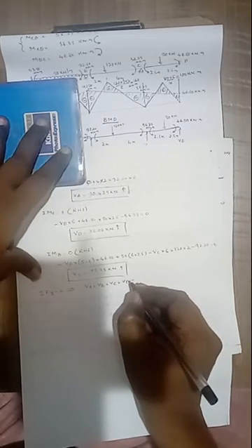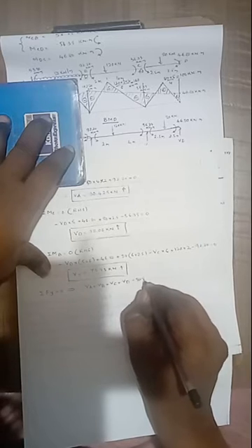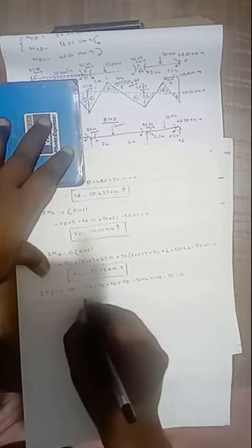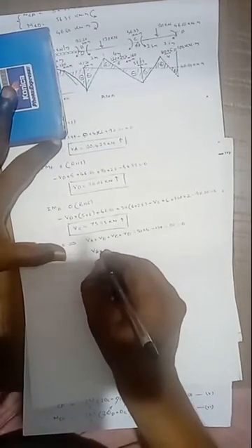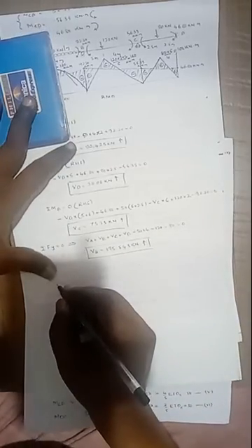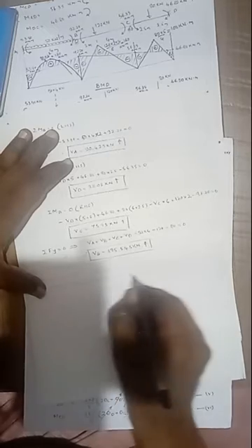Then by the equilibrium equation, summation of Fy equals 0, we get VA plus VB plus VC plus VD, all assumed upward, minus the downward forces: 50 into 4 due to the UDL, minus 120 point load, minus 80, all downward. The summation of all these equals 0. Since we have calculated VA, VD and VC, VB at B is 195.545 kilonewton, which is also positive, that means upward. Now we have calculated all the support reactions. Then to draw the shear force diagram, start from one end, with VA, VB, VC, VD.